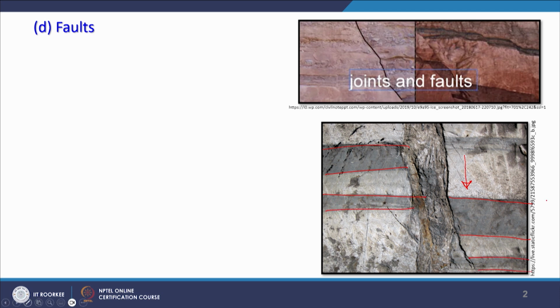If it is an impervious bed, or fine grained, say clay kind of sediments, then we have to understand on a larger scale, and even on a local scale, what would happen. What I am trying to say is that if drilling is done on this side, this is a confining aquifer condition, then you would get water at this depth, but if drilling is done here, then water will not be available at this depth. In confined aquifer condition, it would be available here. So, a fault in between two bore wells can create a different depth for the availability of water.